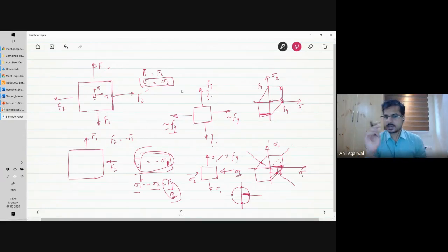Okay. So from here, if I ask you, if I have an element which has only shear stress of tau acting on it. According to Tresca criterion, when will it yield? At what value of tau will it yield? In the third direction, there is no stress, only a biaxial situation. Only tau is acting, like so. At what value of tau will it yield?